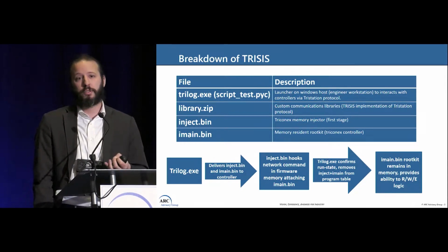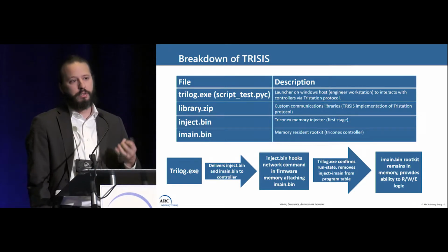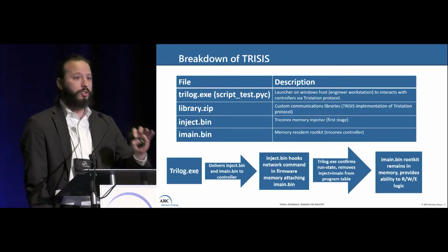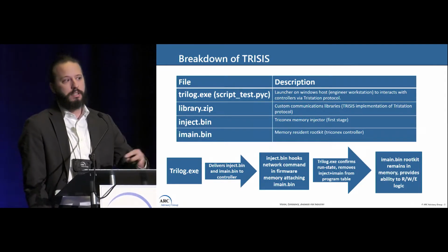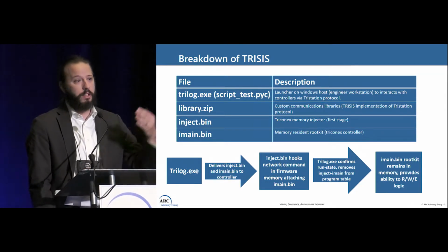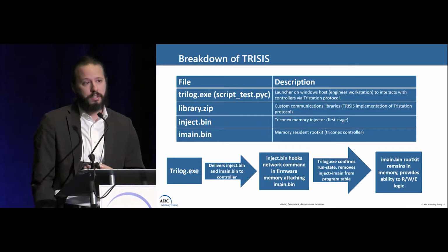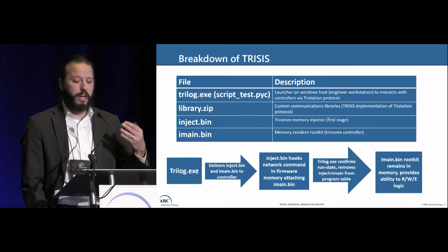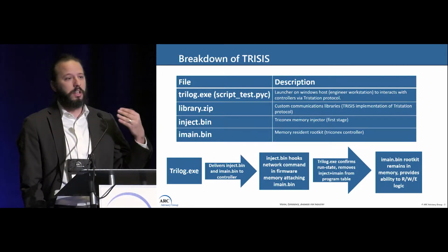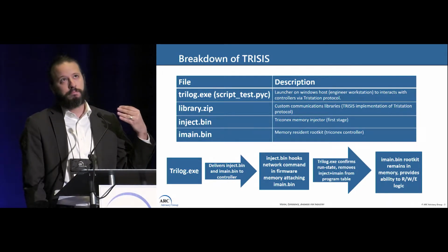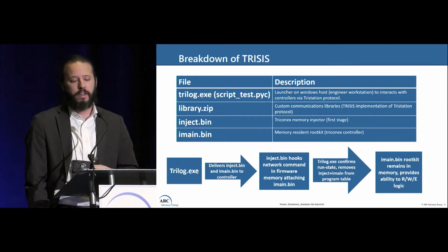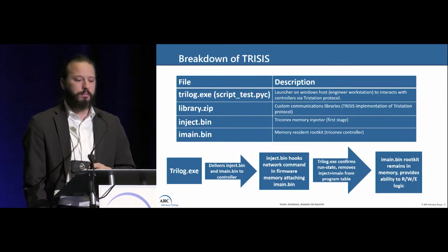So it's in stealth mode, and it can arbitrarily read, write, and execute memory on the controller, and that's dormant on that box going forwards at that point. And it won't show up in the program list if you access that from the engineering workstation. So basically, you have persistent access to the controller by the adversary in a stealth fashion, and that's what they were testing. Ultimately, that is what it comes down to.